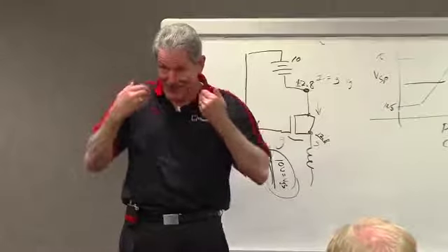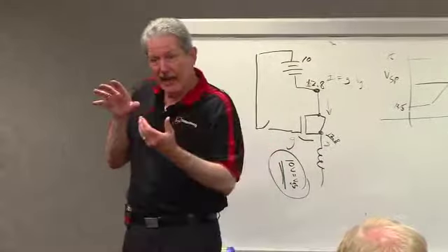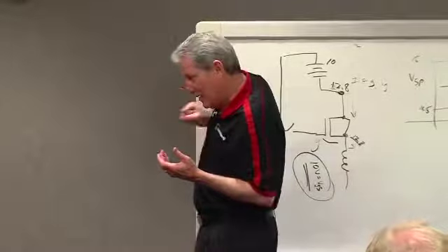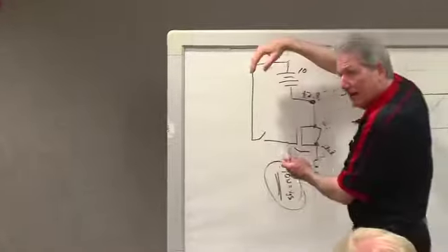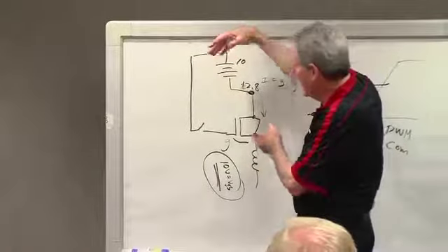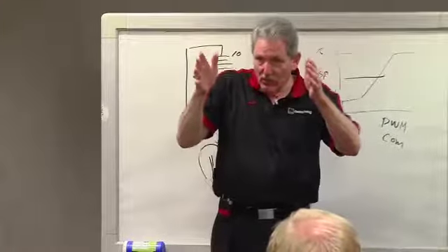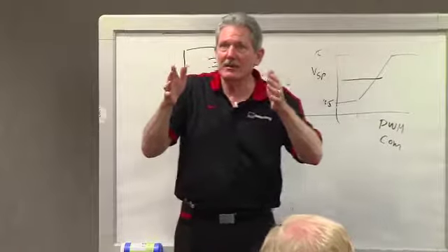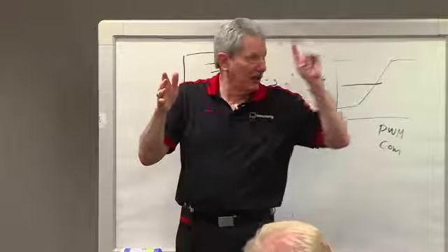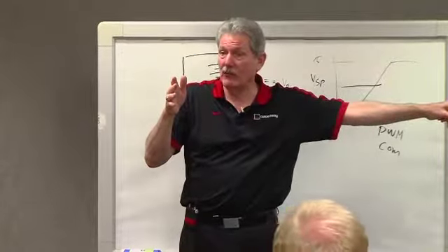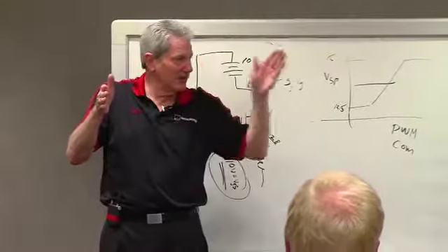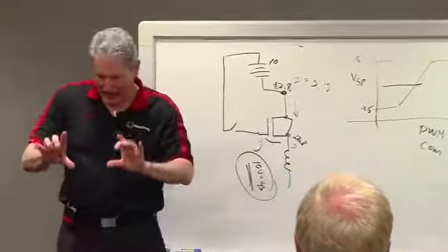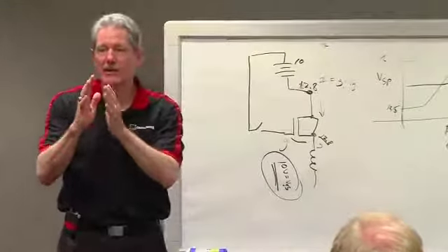So now he sends all that information, and the regulator takes it, grabs each one of those bytes, and stores it. Then, behind the curtain, takes that and says, "Okay, now this is 110111. That means set point 14.8." So it now says set point 14.8. It takes that other byte, it decodes that and says load response control 2.5. And it's an interactive communication.